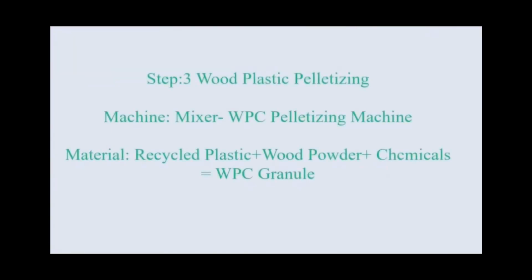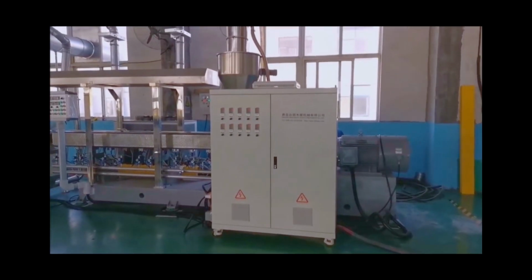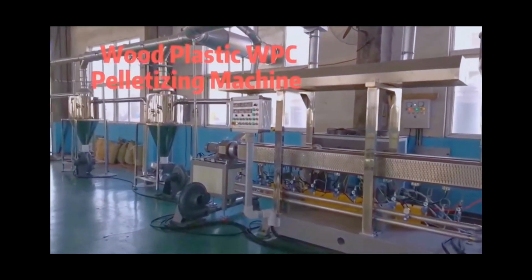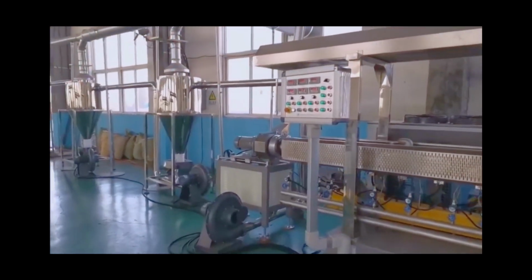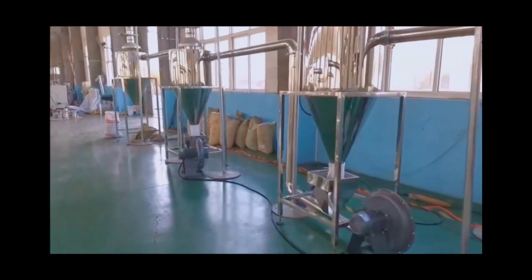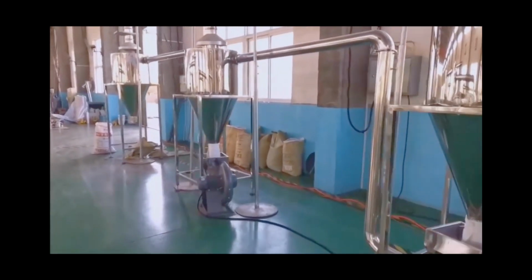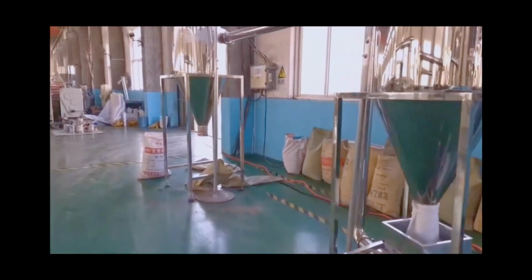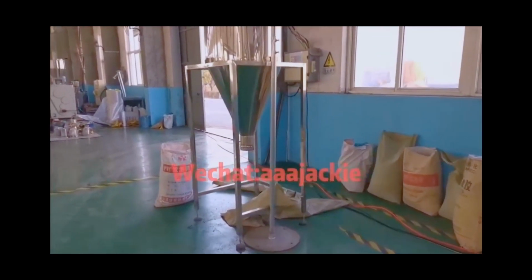So the next step is the mixing of this wood flour with the matrix and pelletizing. So this is typically a twin screw extrusion process, and then it can be extruded using a single screw extrusion process with a die that has the shape of the final product.